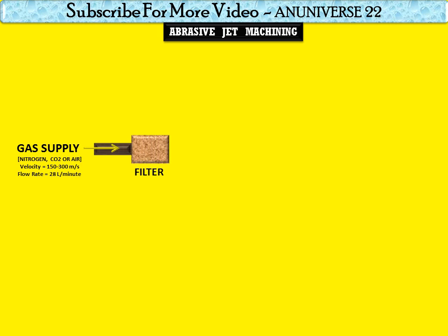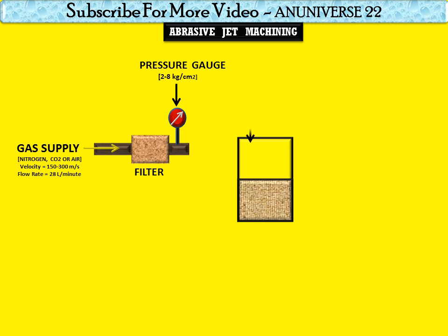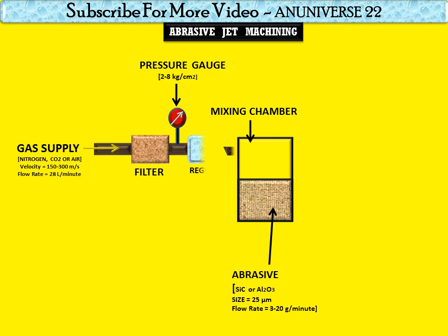And this is the filtration of the gas supply, with the help of a filter. On the next step, here is the pressure gauge, and the pressure of the gas is maintained between 2 to 8 kg per centimeter square. And after that it passes through the mixing chamber, and the gas is supplied with the help of a regulator. So from the regulator this gas comes into the mixing chamber,